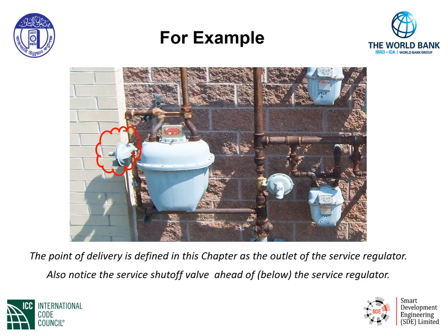For example, the picture that we're showing here is an indication of point of delivery. So the point of delivery is defined in this chapter as the outlet of the service regulator. Also notice the service shutoff valve ahead of the service regulator.